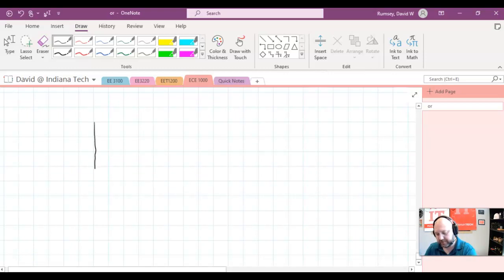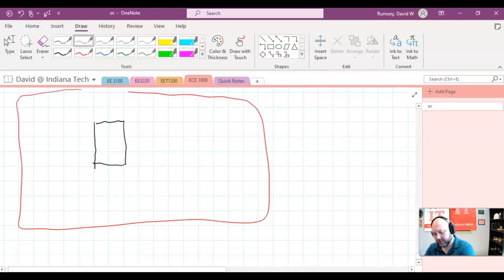I've got some chip here that's mounted on a board. This red here is my circuit board, and then I've got this chip, which will be a surface mount chip, and it's going to have 6 pins on it. Then we have these traces, which I'll draw in red. These traces are the conductive material that is either going to have power or a data signal on it, and it might go along here. I'm trying to keep it the same width, but clearly I did not do it there. It might go along, and then we hit basically a hole, and then the trace ends.